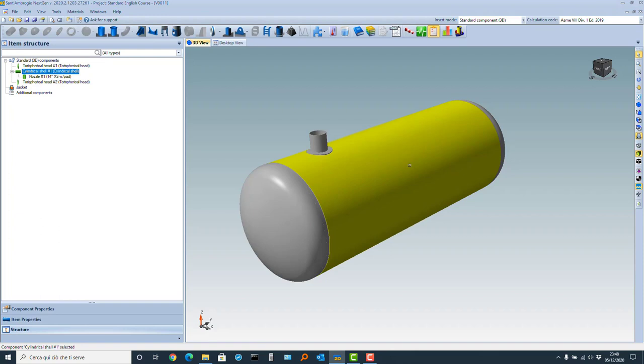Well, it is worthwhile checking if a reinforcement of a 14-inch nozzle could be better achieved using, for example, a long welding neck flange. So we could try to make another nozzle, also with a diameter of 14 inches, but using a long welding neck flange.